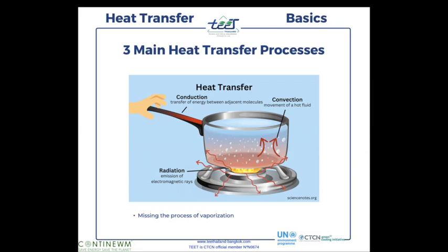The third one is named radiation. Radiation is emission by electromagnetic waves, basically. If you are in a room where, if you take a thermometer, the air is, let's say, 25, but the walls around you are, let's say, 0 degrees Celsius, you will feel cold, even though the temperature is 25 degrees in the room.